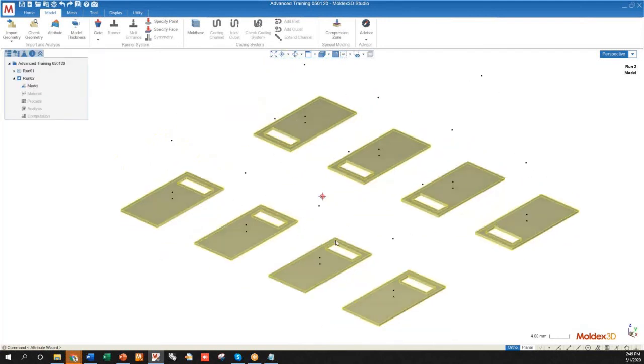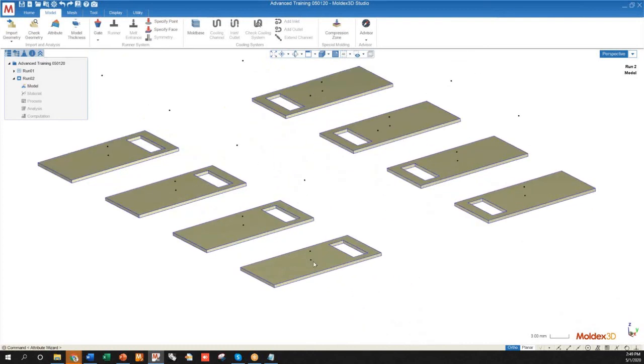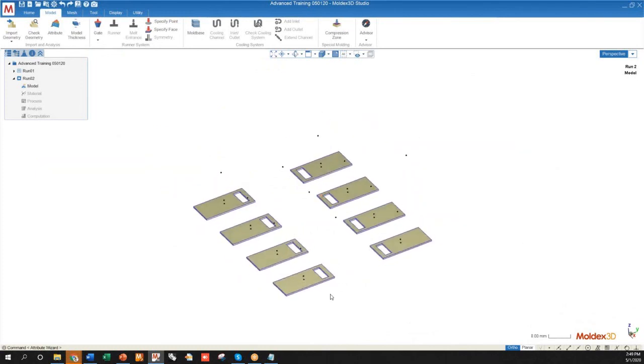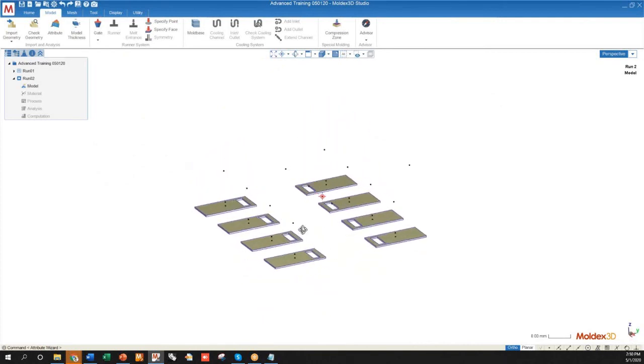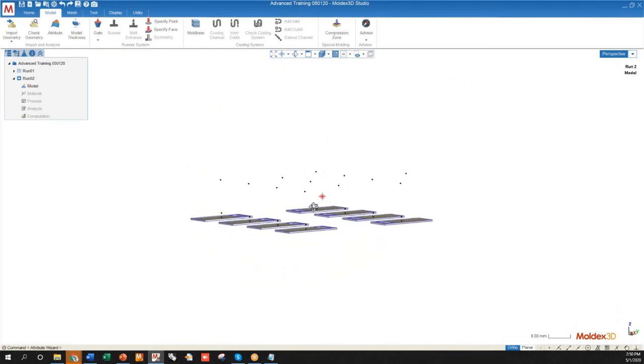Now you'll actually note that the step file that we imported here is able to hold these dots, and step files are also able to hold lines as well. So actually, I see a lot of users importing the lines along with the geometries, and that is perfectly okay. You can do that. The lines, as far as Moldex3D is concerned, if there's lines that don't do anything, that is actually not a problem because Moldex3D only considers objects that have been attributed.